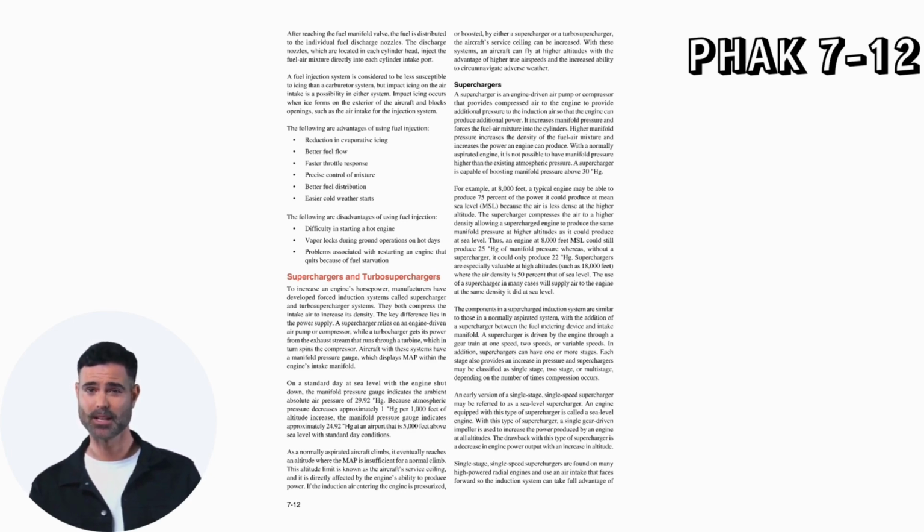As a normally aspirated aircraft climbs, it eventually reaches an altitude where the MAP is insufficient for a normal climb. This altitude limit is known as the aircraft's service ceiling, and it is directly affected by the engine's ability to produce power. If the induction air entering the engine is pressurized or boosted by either a supercharger or a turbo supercharger, the aircraft's service ceiling can be increased. With these systems, an aircraft can fly at higher altitudes with the advantage of higher true airspeeds and the increased ability to circumnavigate adverse weather.